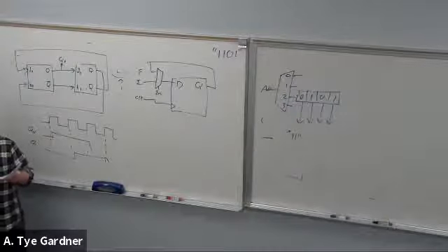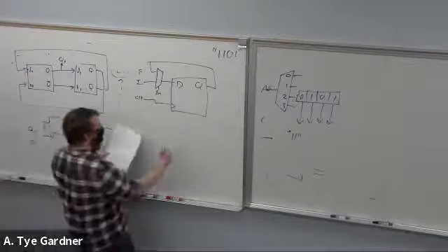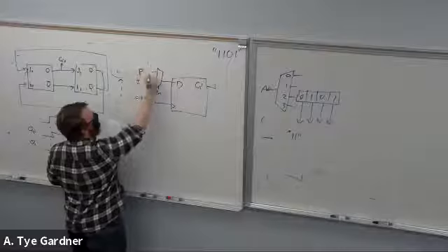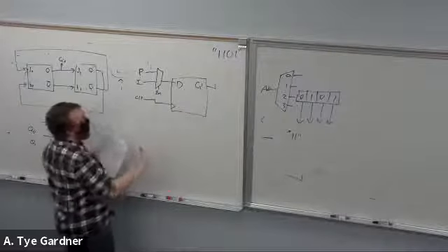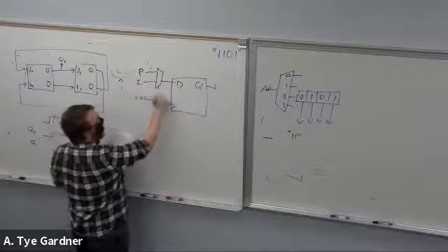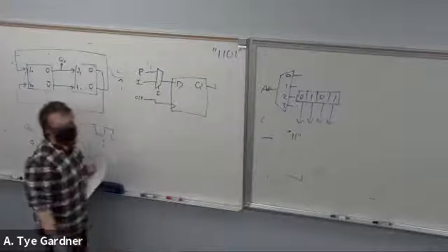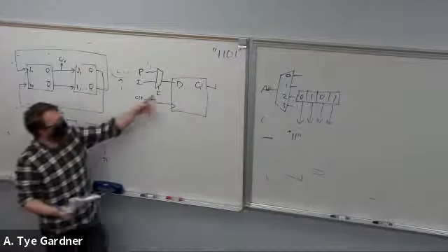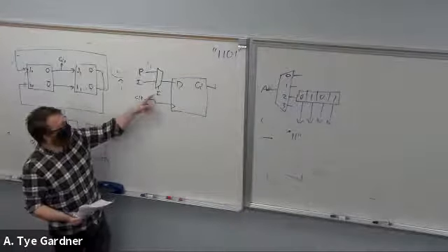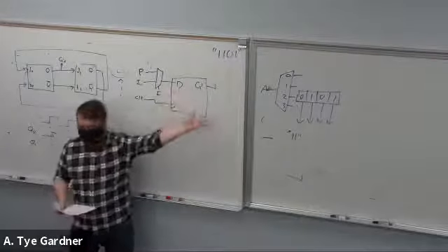On the next one, the D flip-flop, well, I can actually just use this guy. When you want a parallel load, it just takes a mux, right? In this case, it would be not load, it's inverted, right? Because if load is 0, if I select 0, I'm parallel loading. Otherwise, I'll take the input. And then you string those together in a shift register.